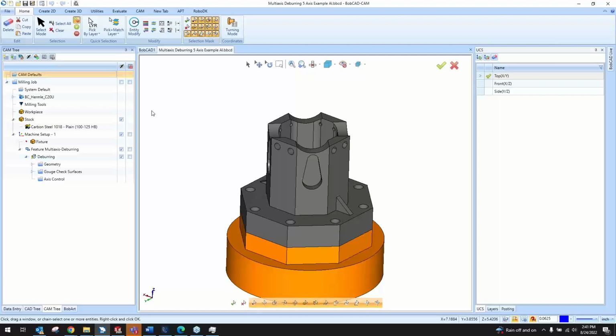So I'd say that's where we're starting with the recognition type of settings that we've got there. We started with holes, and in the near future, I would say we're going along with the machining recognition, feature-based recognition that other people are used to, where you can select a certain area of the part and it will give you a certain tool choice, and you can set up for tool deflection and things like that.